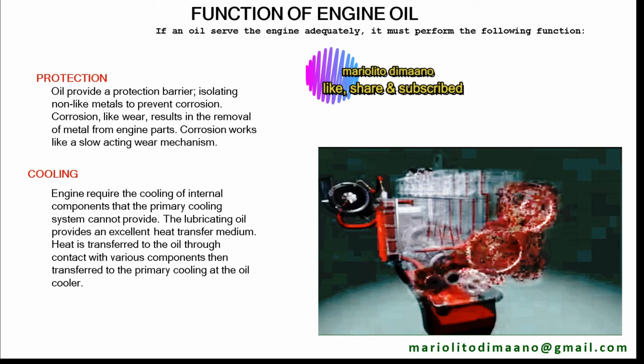Cooling. Engines require the cooling of internal components that the primary cooling system cannot provide. The lubricating oil provides an excellent heat transfer medium. Heat is transferred to the oil through contact with various components, then transferred to the primary cooling system at the oil cooler.